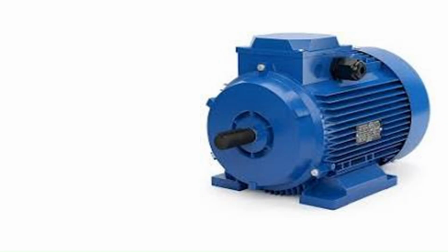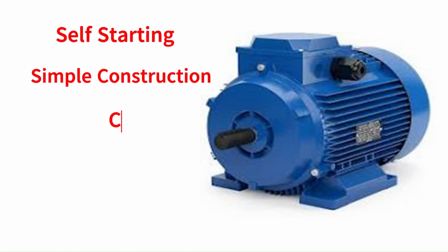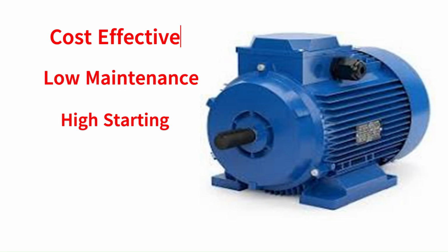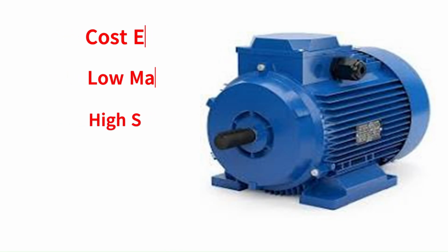Three-phase induction motors are characterized by their self-starting ability, simple construction, and relatively constant speed that varies with the load. They are cost-effective, require low maintenance, and have a high starting torque.